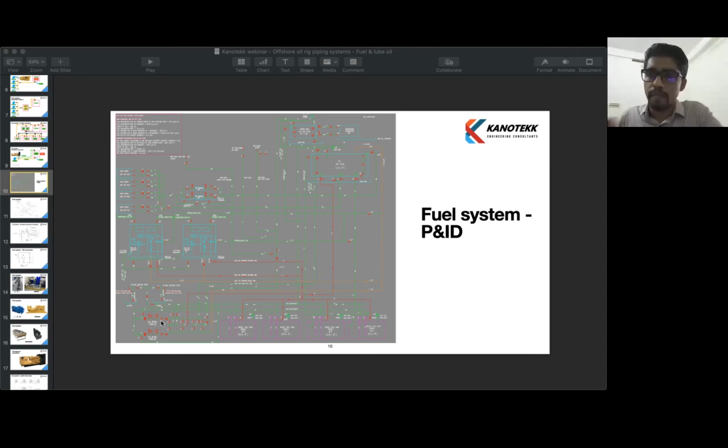If transferring to mud pits, that may require higher flow rates. In such a condition, we can use centrifugal pumps. A separate centrifugal pump, apart from the transfer pump, can be used for transferring stored fuel oil to the mud pits. In that case, we can go for higher capacity pumps because of the centrifugal pump advantage.